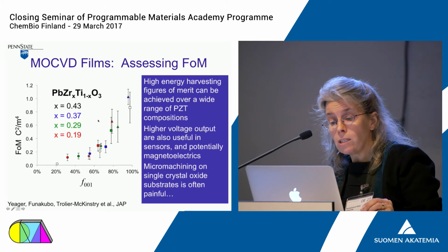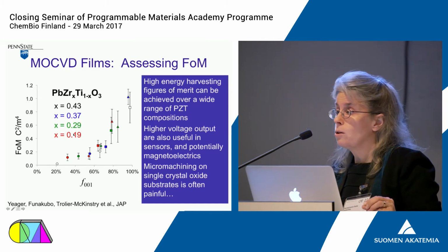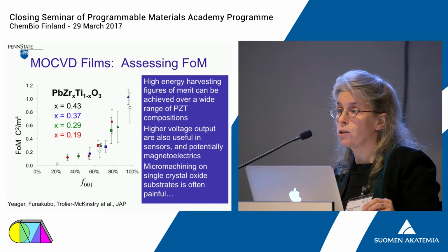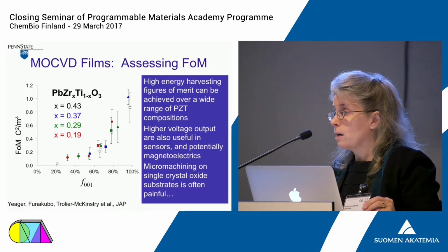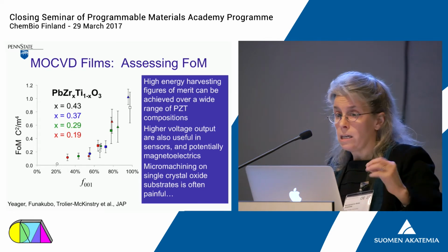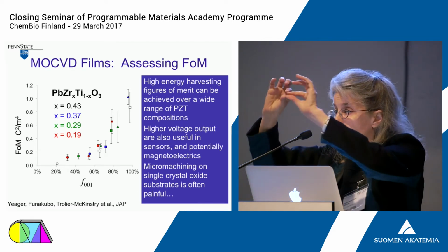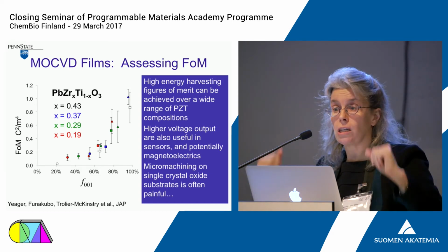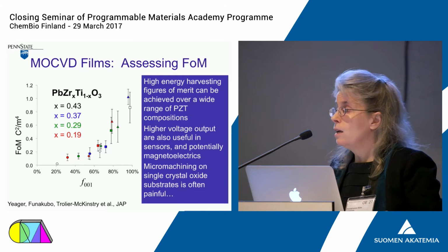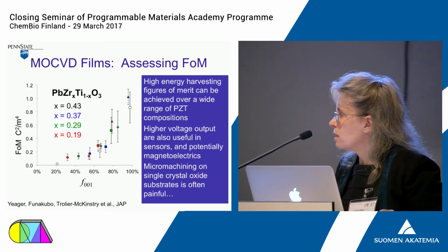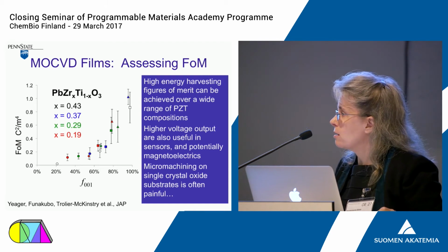So the substrates we utilized for this application were substrates like calcium fluoride or magnesium oxide or strontium titanate, nice ionically bonded solids which are inherently brittle. And we need to make a functional energy harvester, make something that's very thin and hang a heavy weight on it. So we now need to machine this brittle material. And it turns out that absolutely everything that etches those substrates also etches lead zirconate titanate.